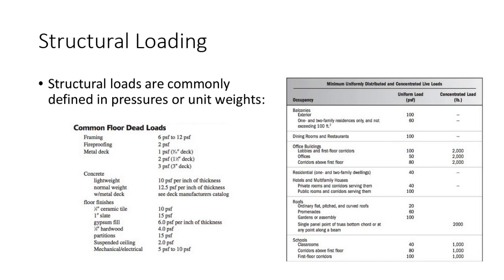And we tend to spec out a lot of structural loads like this, not just dead and live. For instance, when you look at your snow loads, we have a tool that, based on our latitude and longitude, we can determine a ground snow load for our location in the country, and then we can convert that to the loads that we would use on the roof, but it's spec'd out in terms of pounds per square foot. Same thing with a lot of other forces. So where does the load come from? Well, it comes from the structure itself, and it depends on what you're using the structure for.